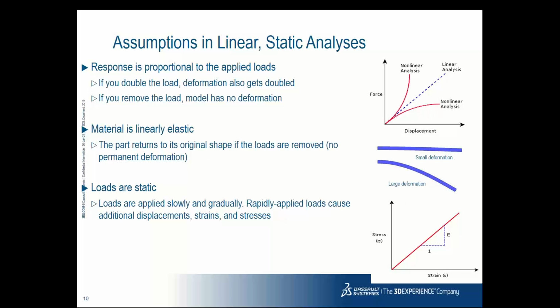So now I'll talk about linear static analysis. This is the first and very basic analysis that we will be covering today. So what exactly is linear? You must have learned in your strength of materials that elongation is equal to FL by AE, that is force times length divided by cross-sectional area times Young's modulus. So the first assumption is that linear static analysis is elastic in nature.